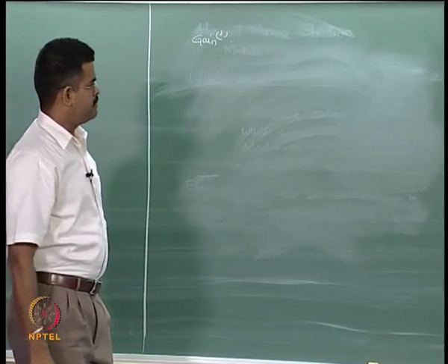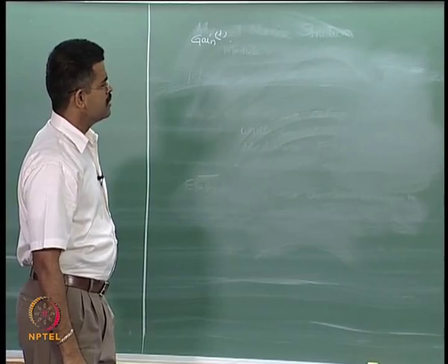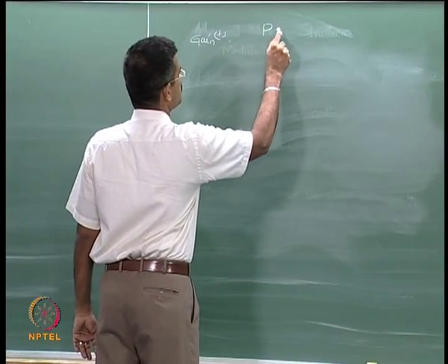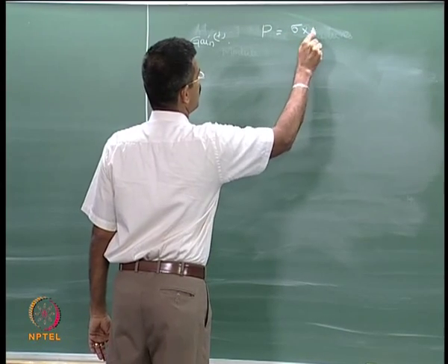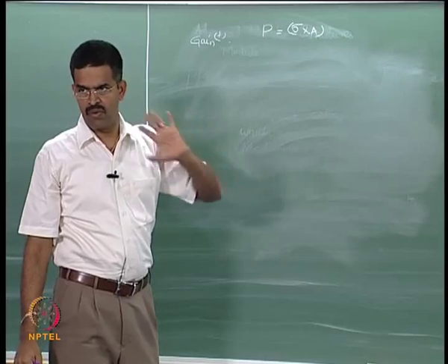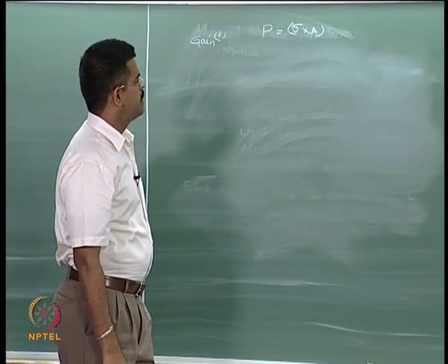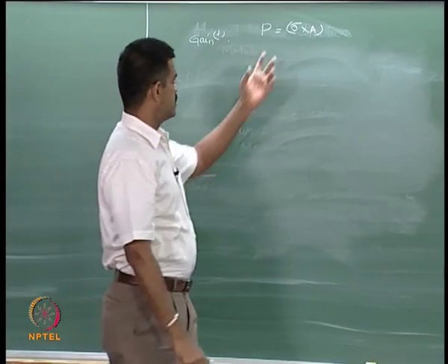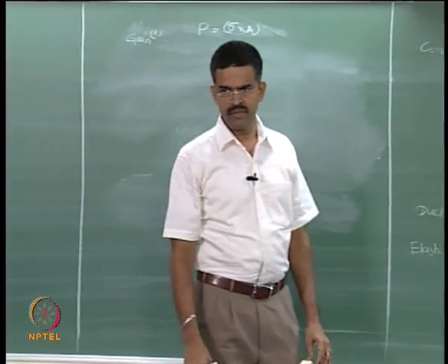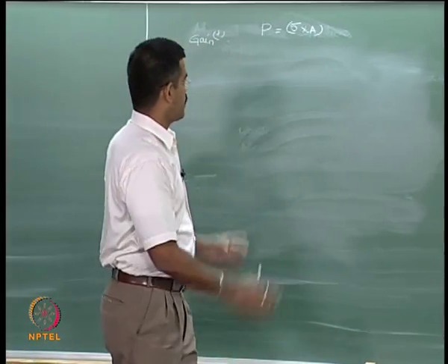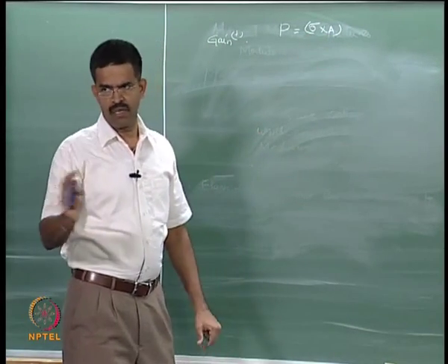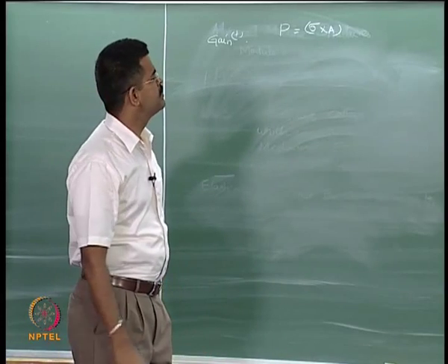Now, the gain what you get is the load carrying capacity. As we all know, load carrying capacity is simply equal to stress by area if it is an axial loading. If it is bending, then the sigma y into z and all, okay. Of course, it is not as simple as this equation when you go beyond the elastic region, but let us say understand that it is a proportion of the stress and the cross section area or section modulus, depending upon what kind of loading you are looking at.